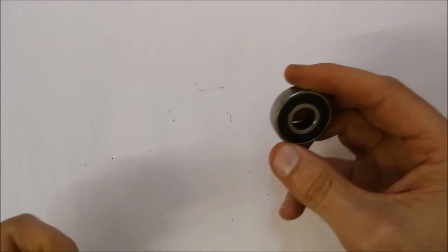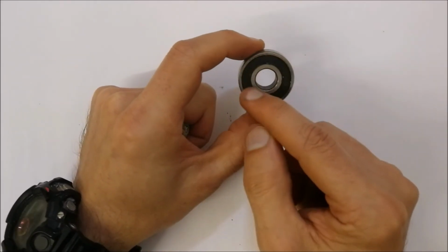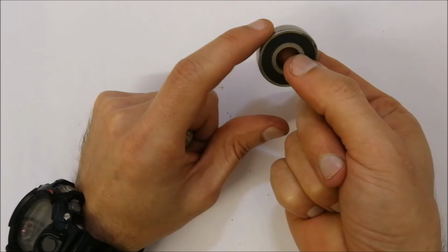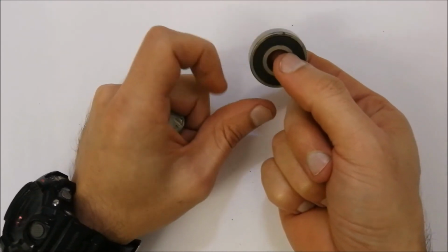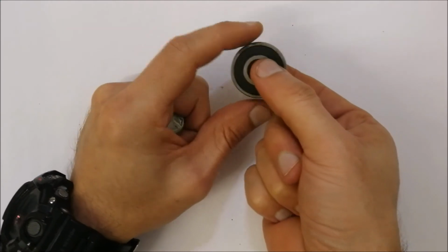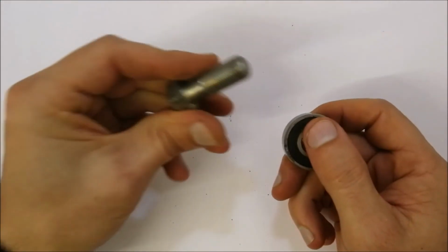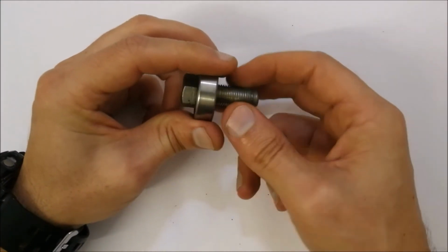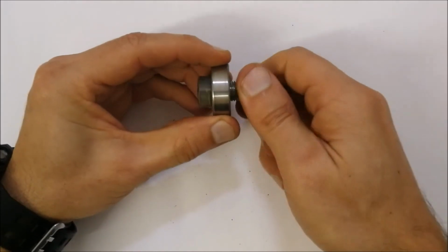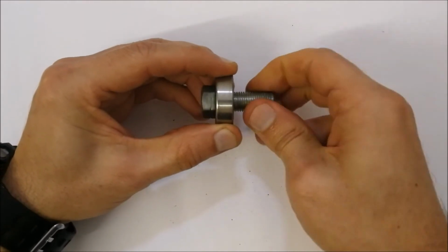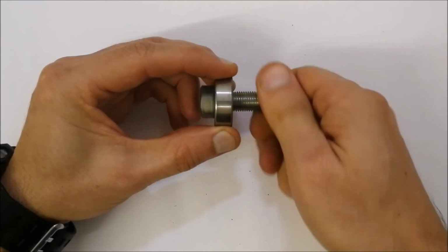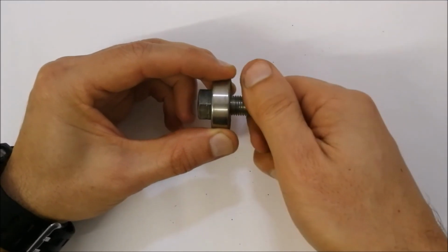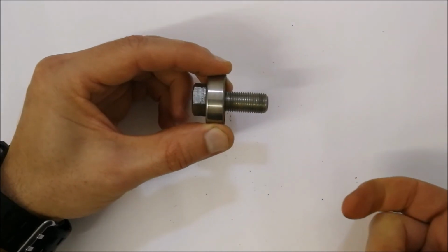A bearing essentially has little ball bearings, little balls over here where the plastic is, and that allows the inner part to rotate much more easily compared to the outside of this bearing. So essentially I can have a bolt like this or some shaft that I place inside over here, push through onto the bearing, and now if I hold this bearing, you're able to turn this quite easily, and you'll actually see that this bolt or shaft that I have in here will be able to turn and spin very easily compared to the shaft that was in the bush.